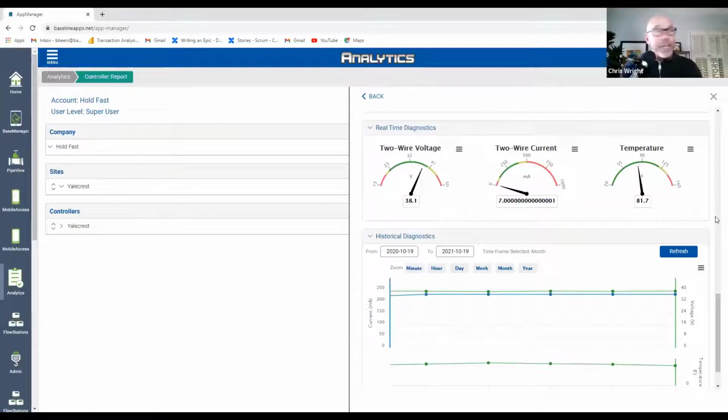Exactly. Great question came in the chat. Is this 3200 centric, or can we get the same info for the 1000? So currently, from when we released it, it's specific to the 3200. And to expand on that, it's actually 3200 controllers that have a firmware version of 17.9 or higher. We'd recommend you go to 18.1. That's now available, regardless. But at 17.9 is when we'll be able to expose different electrical diagnostic data down to a minute resolution.